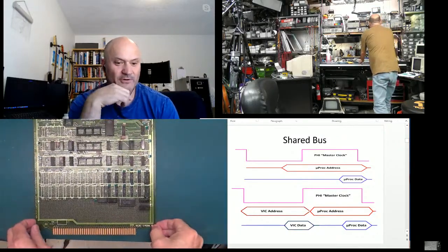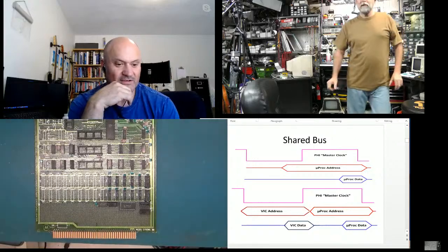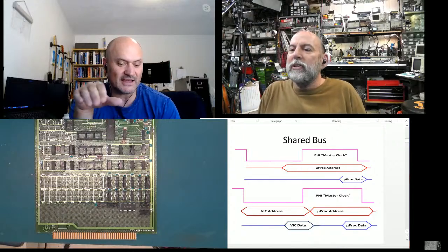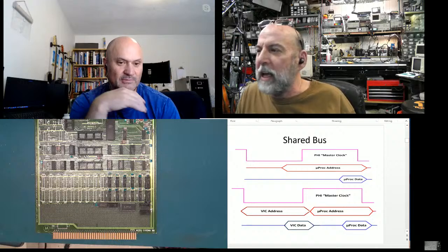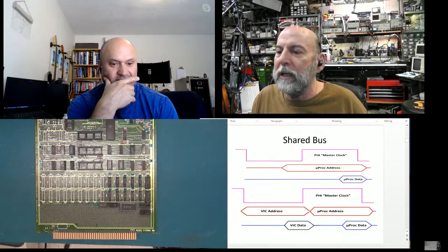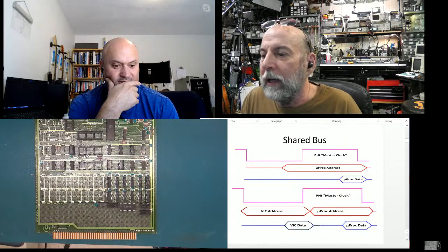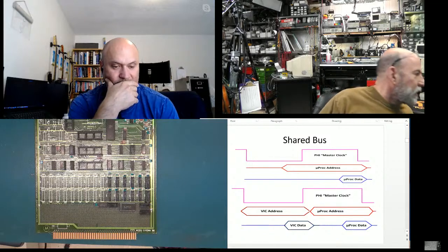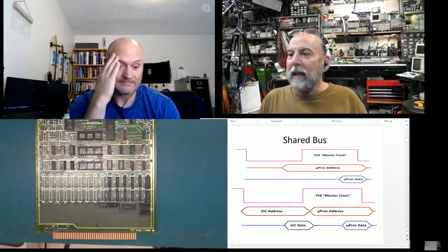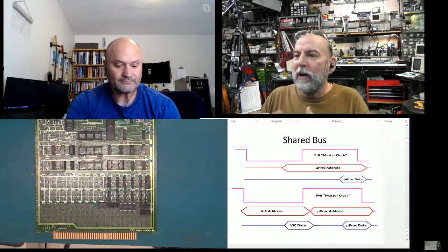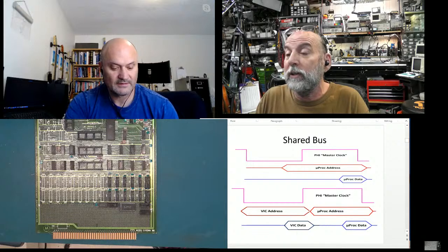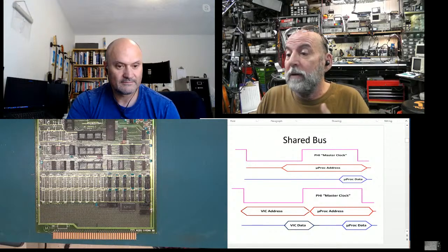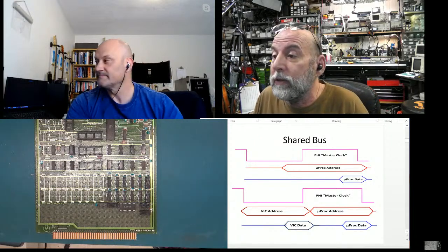So what's the bus on the bottom of that? I assume this Motorola board was some sort of development kit. But this was a card edge connector on the bottom. Did that follow a standard? No, it wasn't a standard. It was just a way to get voltages on and off the board, so I would have had an edge connector. I have an edge connector around here that fits a KIM-1, and so it's like what's on a KIM-1. You have +5, plus 12, for your DRAM, for your static RAMs. And then some address and data bus stuff probably came out as well.